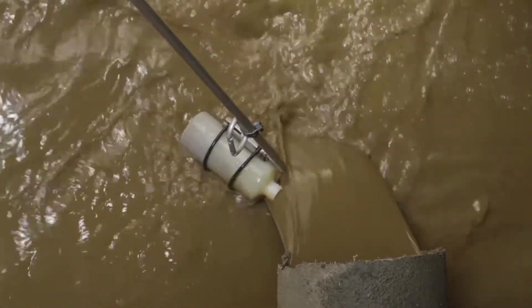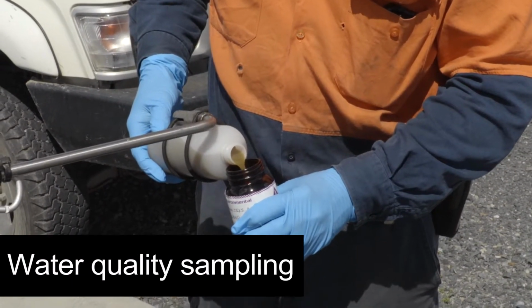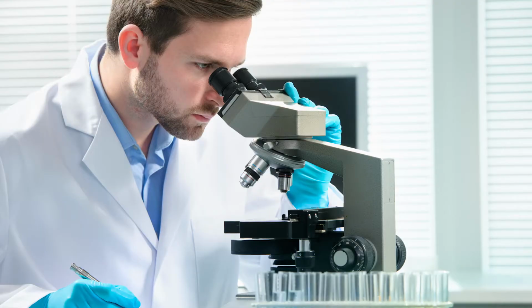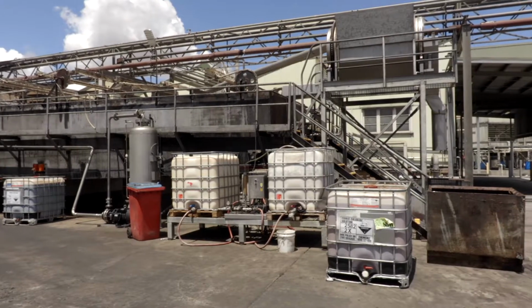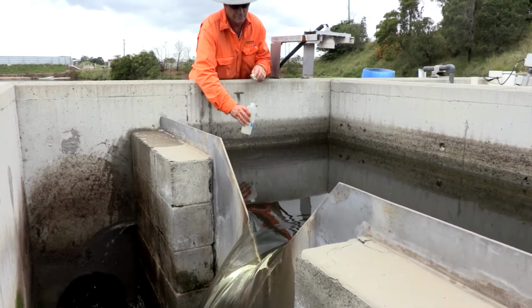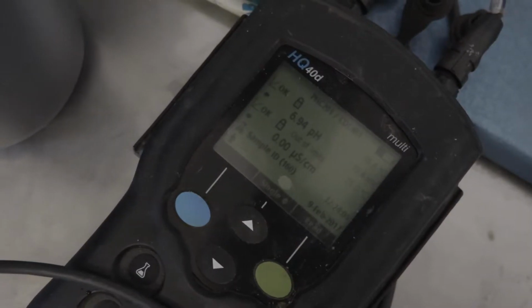The degree to which upstream processes need wastewater quality monitoring depends on the unique features of the plant. Twice a year, operators should collect a sample of the wastewater exiting the upstream process for analysis in an external laboratory. Such measurements need to be undertaken by people with experience in sampling highly variable wastewater streams. Where chemical dosing of the DAF plant occurs, quality monitoring is more important and regular, especially if the DAF-treated wastewater is discharged to sewer. This sampling and testing will typically occur daily at least. The operator may conduct some testing on site to help control the process.